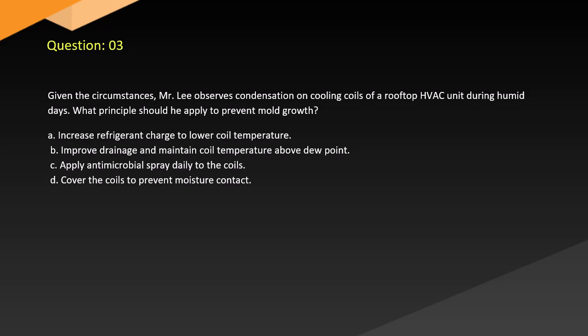A. Increase refrigerant charge to lower coil temperature. B. Improve drainage and maintain coil temperature above dew point. C. Apply antimicrobial spray daily to the coils. D. Cover the coils to prevent moisture contact.